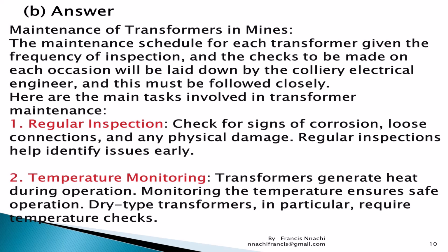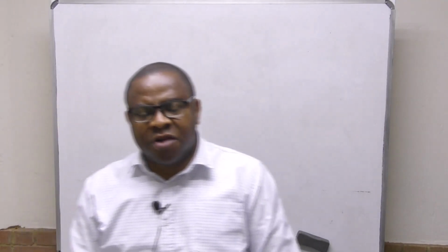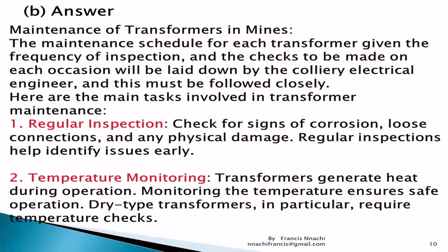And if you have dry type transformers, in particular, they require temperature checks. That's why you have to embed a sensor to check the temperature of this transformer.